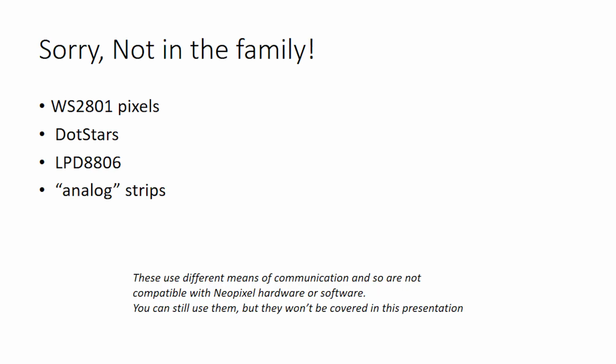So having told you what's in the family, I better tell you what's not in the family. The 2801 was the previous generation before the 2810 series. And they're great, they work as well, but they're not NeoPixels. They're not interchangeable with NeoPixels. Dot stars are a different thing entirely. The LPDs are different. And you get analogue strips that look like a NeoPixel strip, but it's just red, green and blue LEDs. None of these work the same way as NeoPixels. And I'm not decrying any of them. They're all useful in their own ways, but they're not NeoPixels, and that's kind of what I'm here to talk about today.